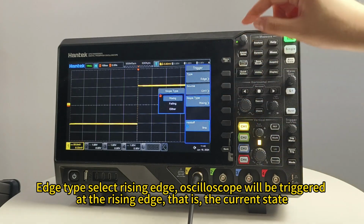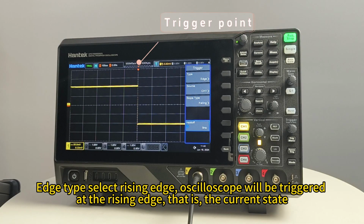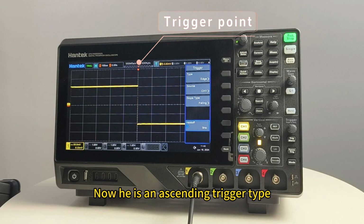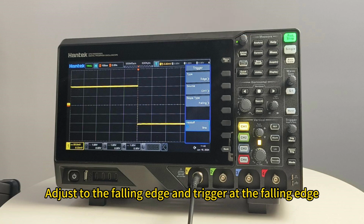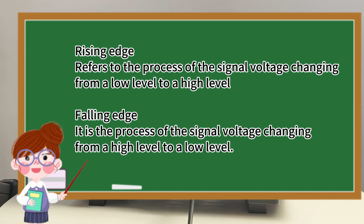For the edge type, select rising edge. The oscilloscope will be triggered at the rising edge. Now this is the rising trigger type. Adjust to the falling edge, and it triggers at the falling edge. Rising edge refers to the process of the signal voltage changing from a low level to a high level. Falling edge is the process of the signal voltage changing from a high level to a low level.